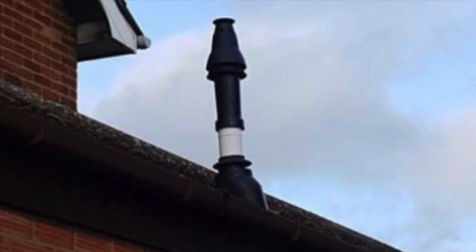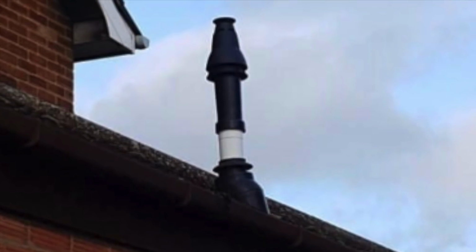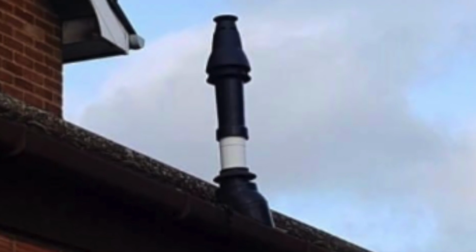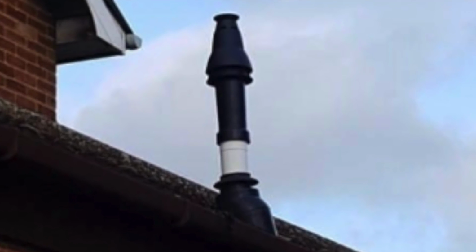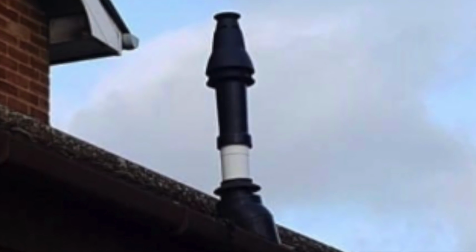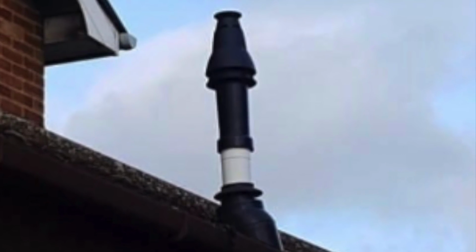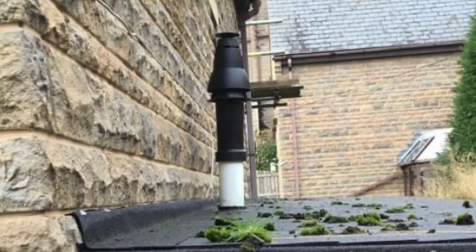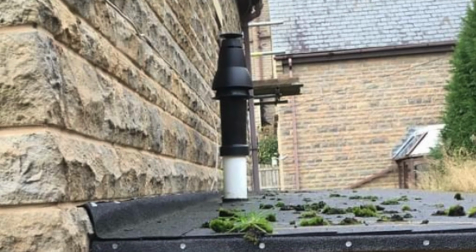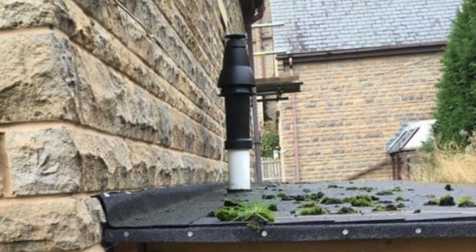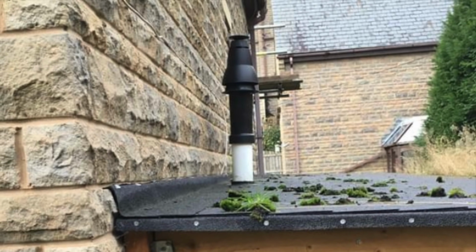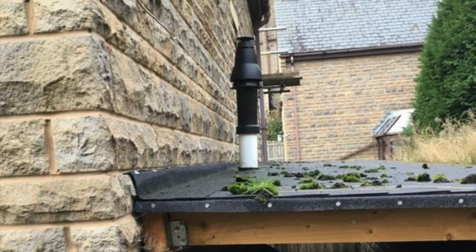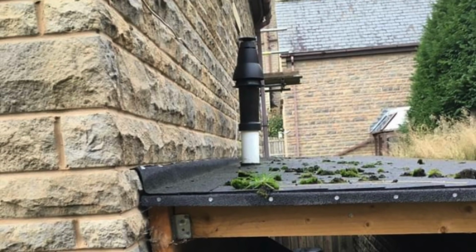Now here's a couple of vertical flues which are installed incorrectly. So you can see from this first picture we've got plenty of white showing on the flue. No matter what the manufacturer is for this flue, we should not be seeing any white part of the flue. It should be fitting flush with the weather collar. And again, if we look at this one, it's got loads of white showing and it's too close to the wall. Should be at least 500mm away from the wall. So again, we must follow manufacturer's instructions, and I can't understand why these flues get installed incorrectly.